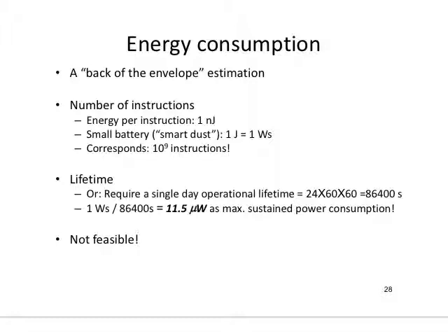That's why I asked you whether it is enough to power the sensor. Remember that the harvesting part is renewable, while the battery has a certain capacity and that's it. Whether it's enough or not is another story. You have to anticipate the amount of energy that you will get through a certain duration of time.